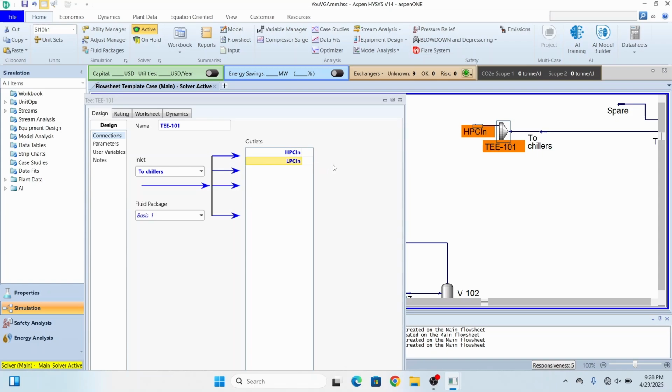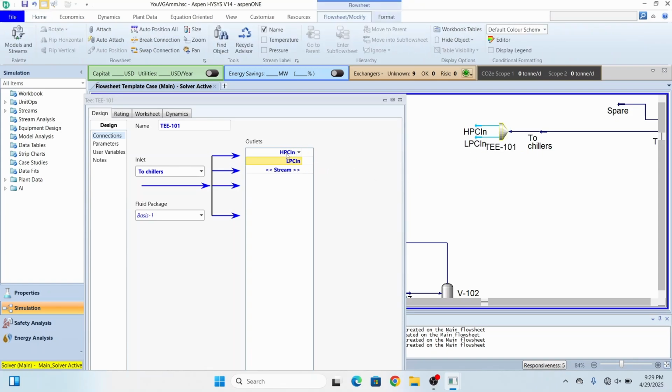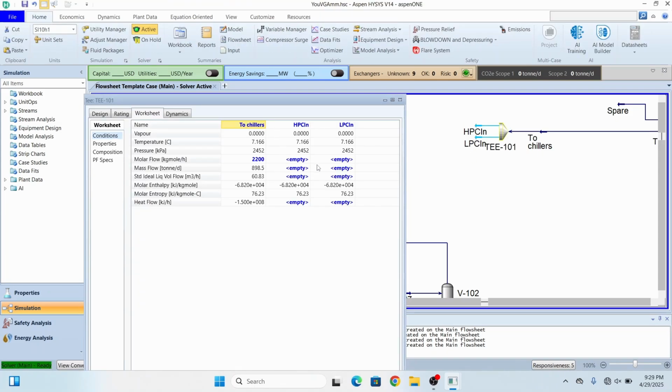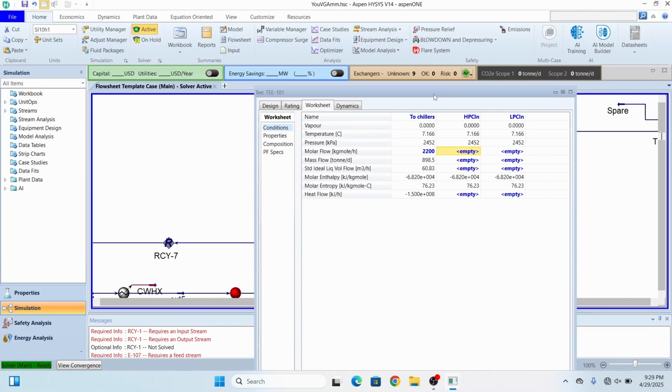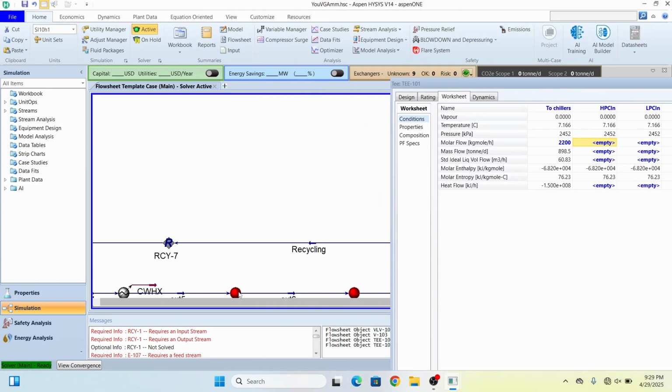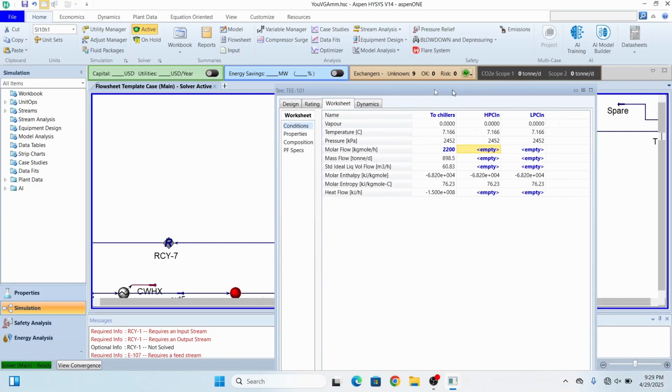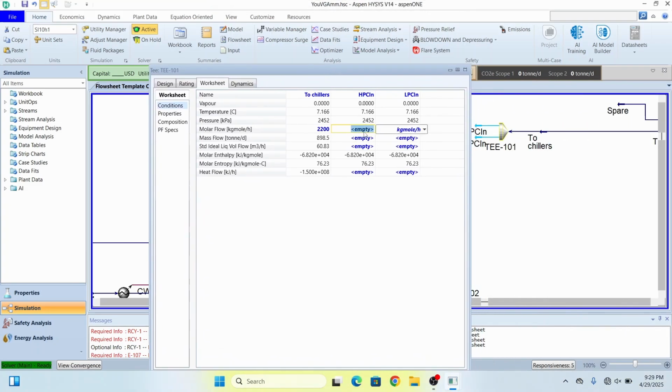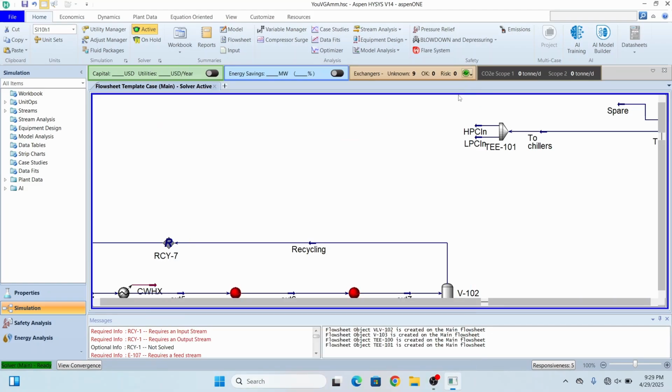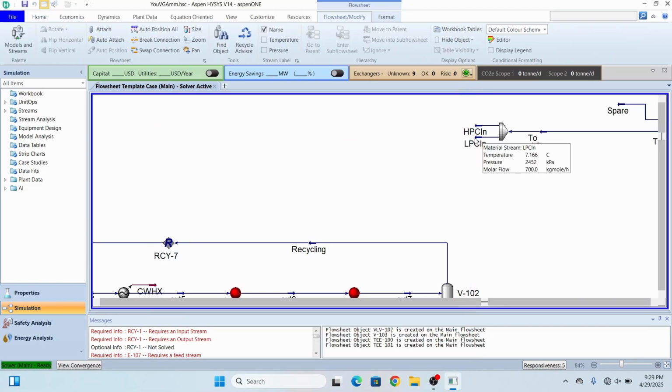So that is good. So now again I have to specify my split ratios. Here, as an addition, because in the high pressure chiller the temperature change is from 40 to 11 degrees, I think, I will give a larger flow over here. I can give 1500 kg/s to this high pressure chiller. So now what will we be doing after this?